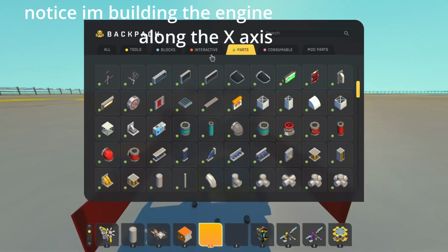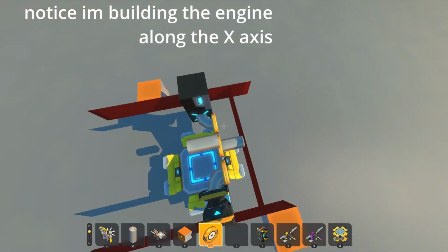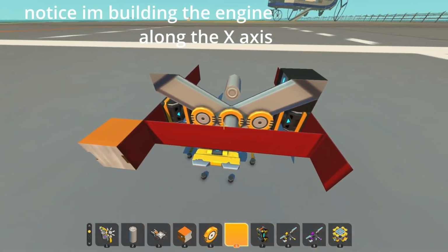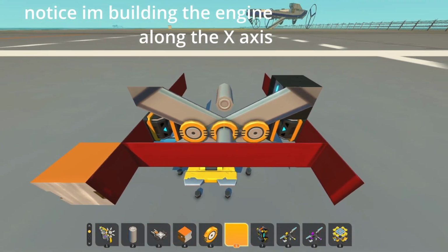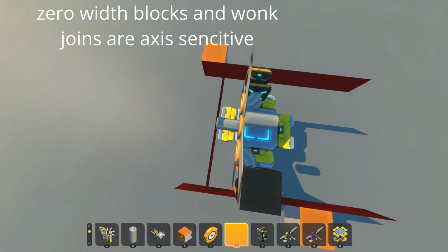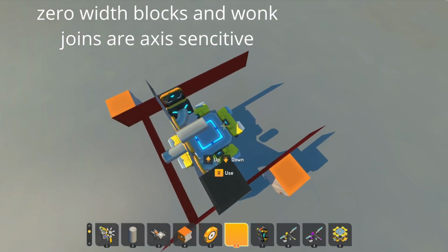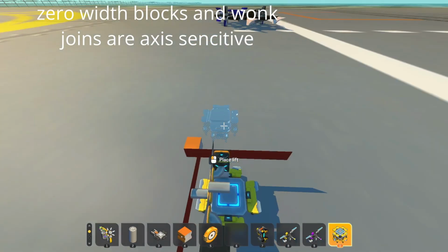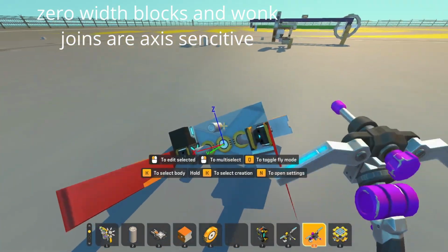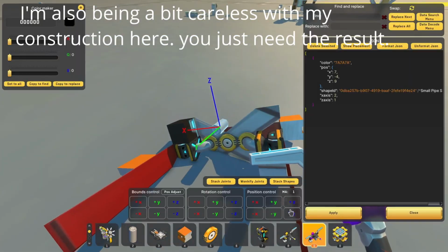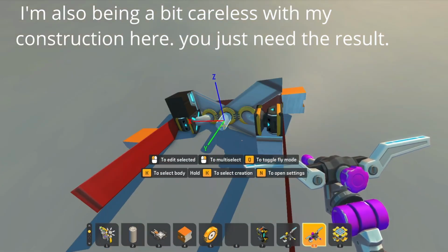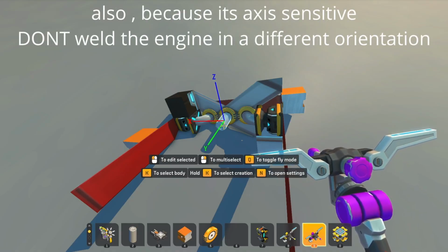I'm going to do this again. So, okay, I built a flywheel off of this pipe and that bearing. But because that's there, I would need to mirror this on the other side. So what I'm going to do instead is make the flywheel the parent of the bearing that's supporting it to the crankshaft.